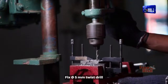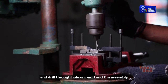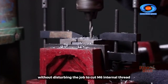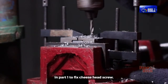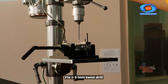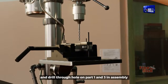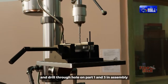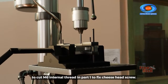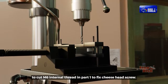Fix diameter 5 mm twist drill and drill through hole on part 1 and 2 in assembly without disturbing the job to cut M6 internal thread in part 1 to fix cheese head screw. Fix diameter 5 mm twist drill and drill through hole on part 1 and 3 in assembly without disturbing the job to cut M6 internal thread in part 1 to fix cheese head screw.